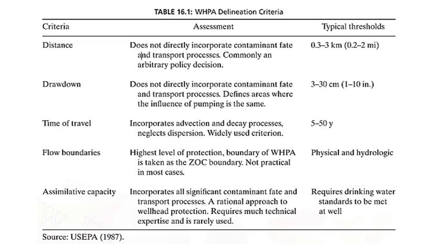Now, the other criterion is the time of travel, which is more or less the widely used criterion. And for the time of travel criterion, we just model the advection and the transport and decay process of the contaminants. So this method neglects dispersion. So it's actually quite conservative because dispersion actually speeds up the attenuation process.